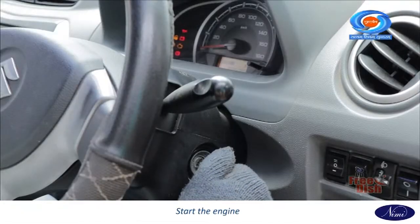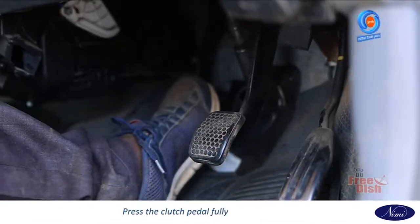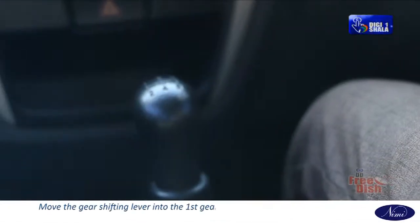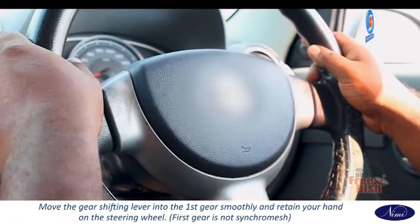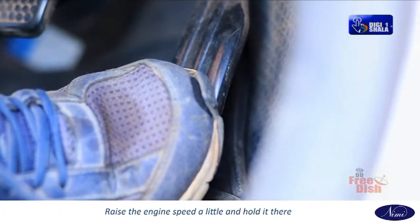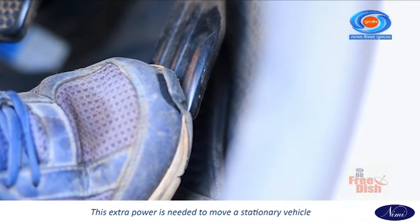Start the engine. Release the parking brake. Press the clutch pedal fully. Move the gear shifting lever into first gear smoothly and retain your hands on the steering wheel. First gear is not synchromesh. Raise the engine speed a little and hold it there. This extra power is needed to move a stationary vehicle.